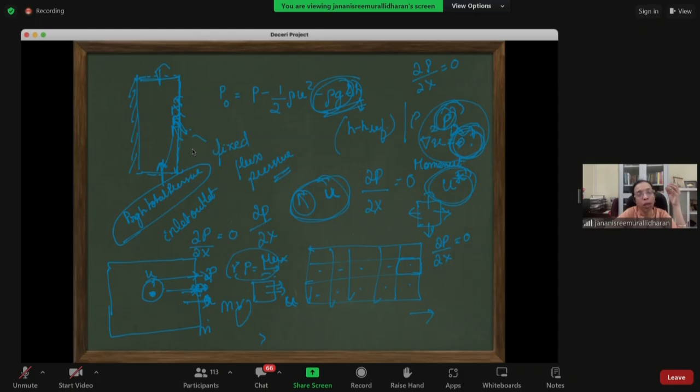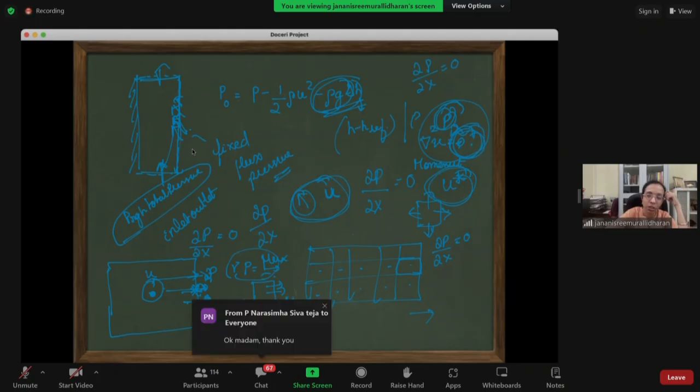Okay. You will know. And then you have to make your mesh lesser so that your CFL number will fall under. So 2 controls are there. Either you make your mesh lesser or your time step lesser. You can only go a little bit lower, you can't go to delta t equal to 10 power minus 10. That may not make sense. So at that time you'll have to adjust. So it's going to be a trial and error process. You can't off the bat estimate your U. Any other questions? Hello, ma'am.